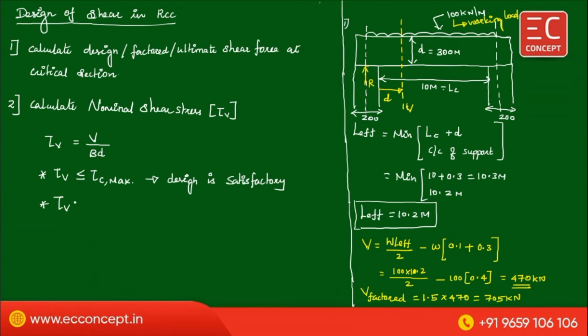If tau V is greater than tau C max, then redesign the section.